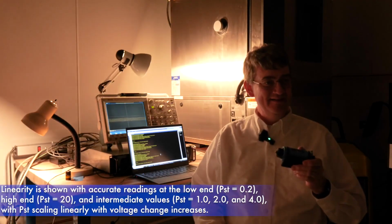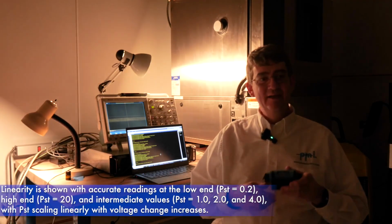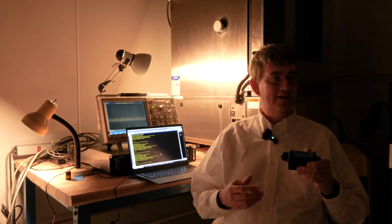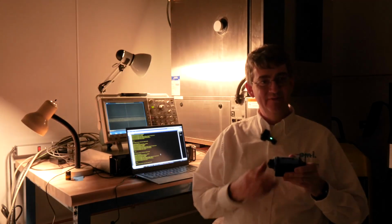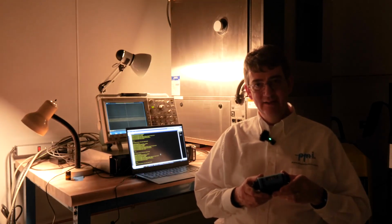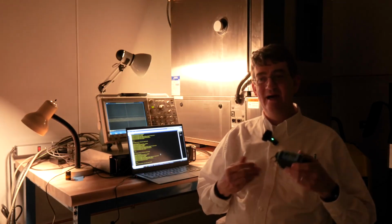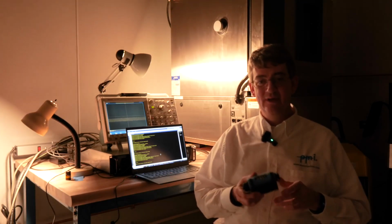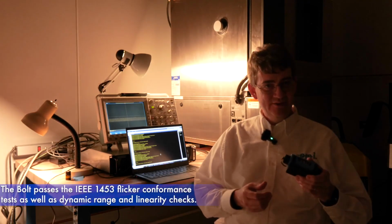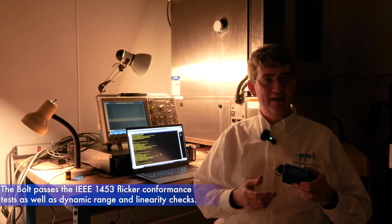All right, we've fully tested the Bolt's flicker measurement ability, and it's passed with flying colors. It met all the conformance test requirements that are in IEEE 1453, and we've gone beyond that to test its linearity and ability to measure very low amounts of flicker and very high amounts of flicker. So it has a good dynamic range also. So the Bolt is perfectly suited for quantifying flicker per IEEE and IEC standards.